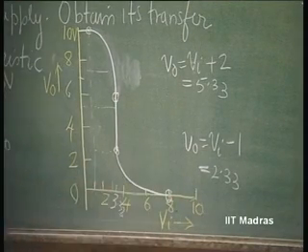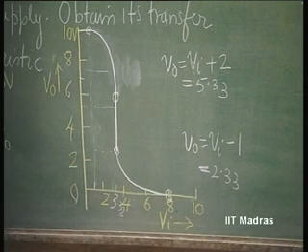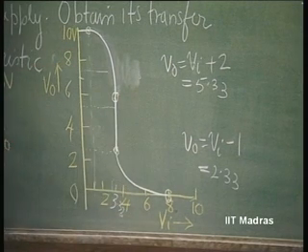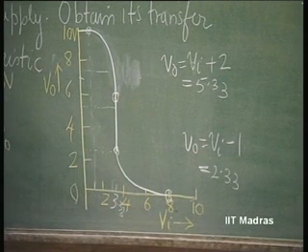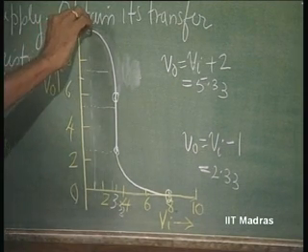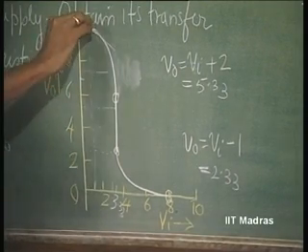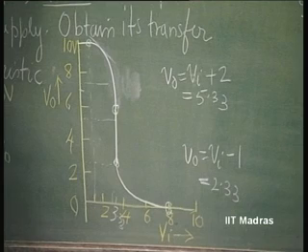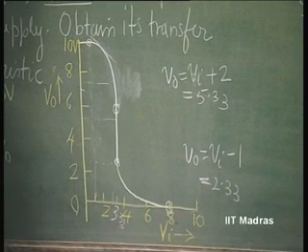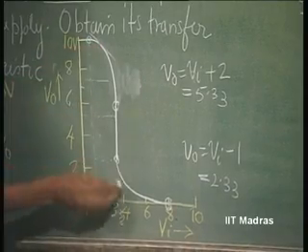This story will go on. After this, transistor T2 will go off. So, this is the complete characteristic of our CMOS inverter. Where if you draw a 45-degree line, what is the slope? Tan 45, that is minus 1 here. You can draw a similar line here.